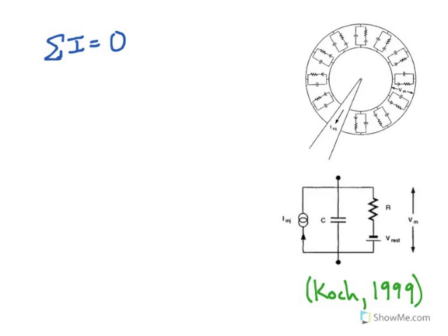So previously we've talked about how all the currents within this electrical circuit need to sum to zero, and that's the conservation of current, or it's called Kirchhoff's law. So we're going to build another mathematical model on this same basis. So before, when we were looking at this law, we had only two currents we had to consider. We had to consider the capacitive current, which we derived from the law of capacitance, and the current flowing over the resistor, which we used Ohm's law to derive.